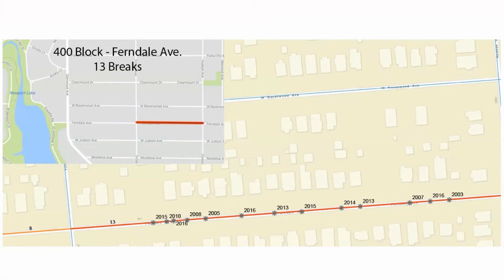Targeting these couple of areas could dramatically reduce the overall number of breaks for the system at the lowest cost, because they'd be doing it on a planned basis with the least service interruption. And then obviously, shutting down those breaks and replacing this problematic pipe is going to reduce water loss. And it's going to allow you to pinpoint scarce resources, because their original plan had been to kind of start at the west end and move to the east end and replace everything in this section. And although everything is going to have to be replaced at some point, it doesn't have to be done now.